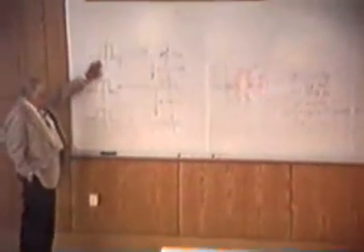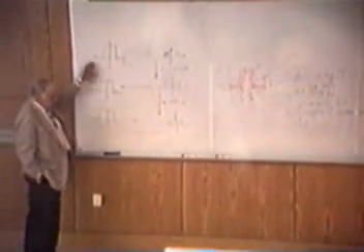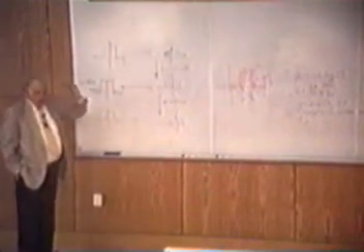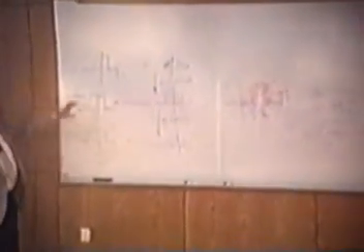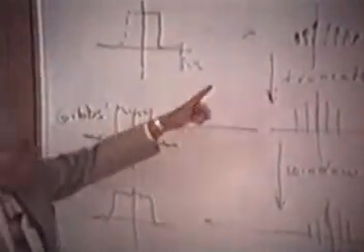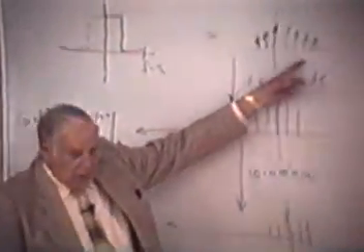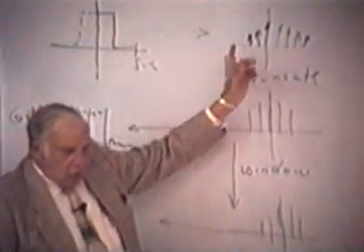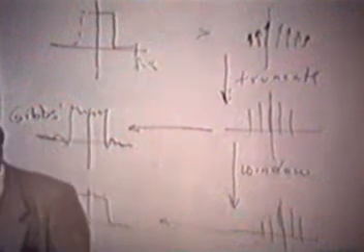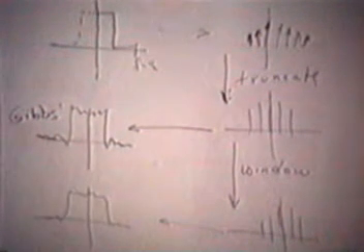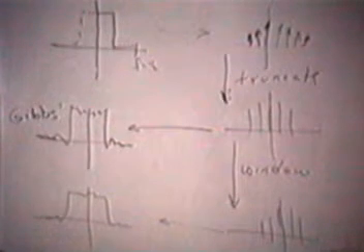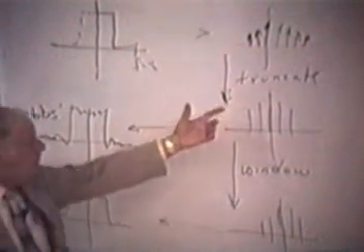So let me discuss the method. Here is the design you want. There's positive frequencies and negative frequencies, and we're working in complex notation. Now, last time I closed with the observation that if I expand this function into a complex Fourier series, the coefficients, which I've drawn here, but they're complex numbers, but I've drawn them as if they were real, those coefficients are the coefficients of a digital filter that does that job. The trouble is there's an infinite number of coefficients. So you have to truncate.